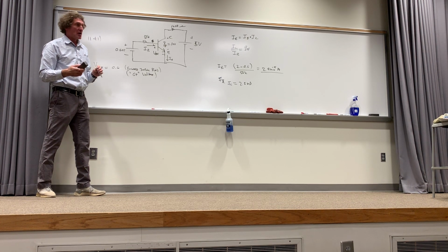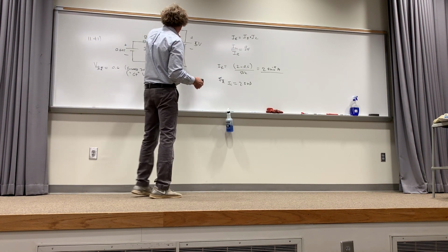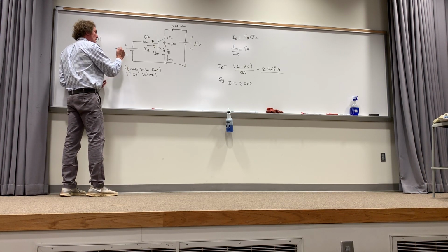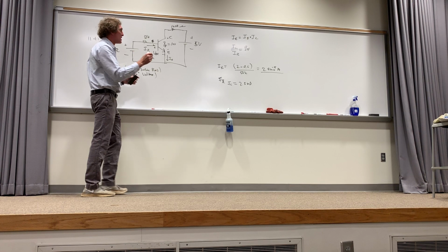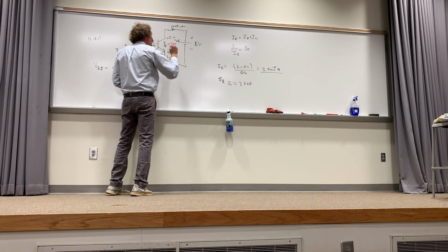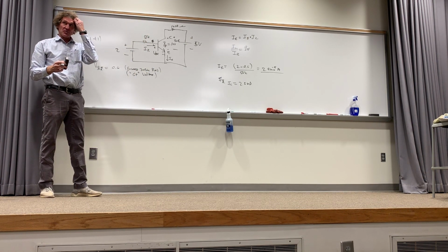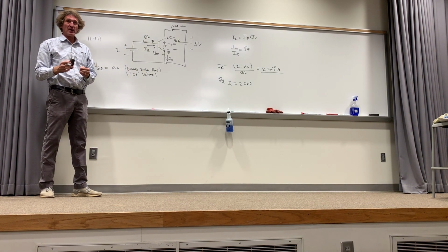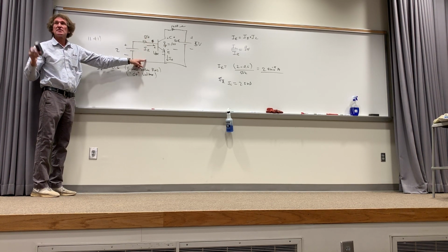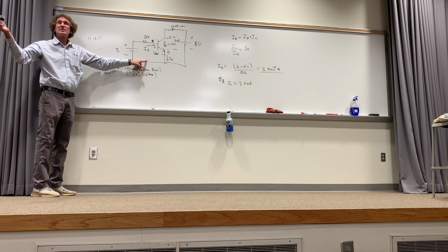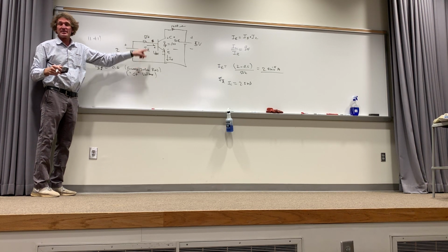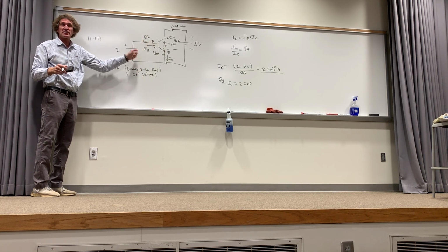All right, now, I put that resistor in, and I'm going to leave this as 2 volts. But now I want a different piece of information. I want this voltage between the collector and the emitter. Everybody with me? It's just one incremental bit different. So first thing is, does IB change when I put that resistor in? Class? How many think it's the same? How many think it's different? It's the same. It has to be, because that voltage doesn't have anything to do with this current.